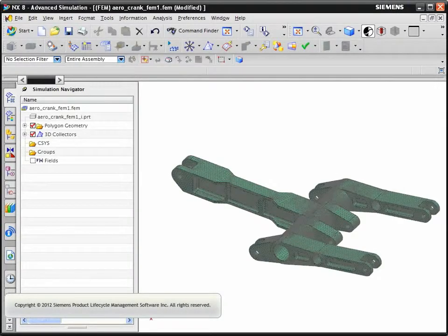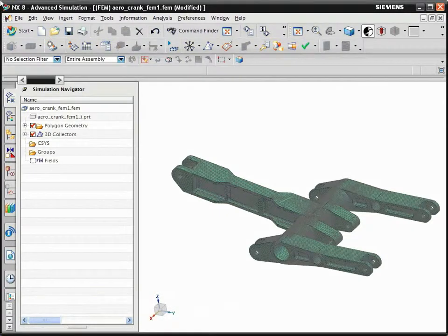In this example, we will use a synchronous modeling command to lengthen the arms of this model. Then, we will update the existing mesh to conform to the geometry changes. In situations where you do not have permission to modify the master CAD part, you can make the geometry changes to the CAE idealized part.